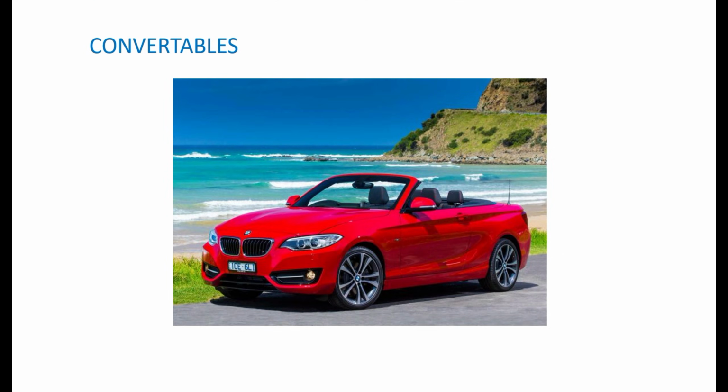So one of the topics we haven't spoken about is bass in convertibles. Now, when I'm talking about convertibles, I'm talking about soft tops versus hard tops, right? So typically in convertibles, it's much harder to get good low-end bass, ultra low bass, below 30 hertz. And there's a couple of reasons for that, but part of it is because of cabin gain, right?